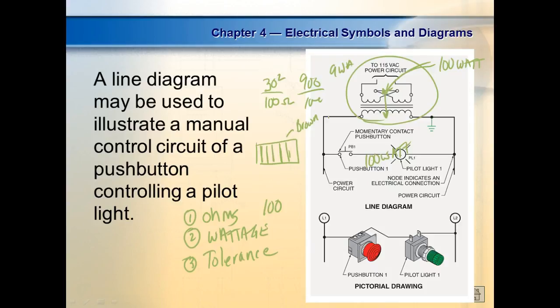But you will run into 5-band resistors, and their tolerance bands are pretty close to what we're going to deal with. Brown would be 1%. Red would be 2%, and I would have to look at some of the other ones.